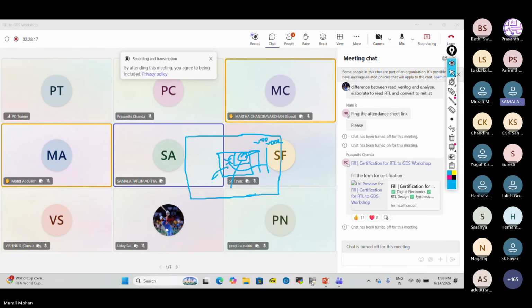Sir, is there anything in the middle of a multi-level design, like placement blockages or shifters? Are any types of cells placed between the two types of designs, like physical-only cells? Multi-voltage cells such as level shifters, you are going to call them. That will be helpful for communication between the two different voltage domains.